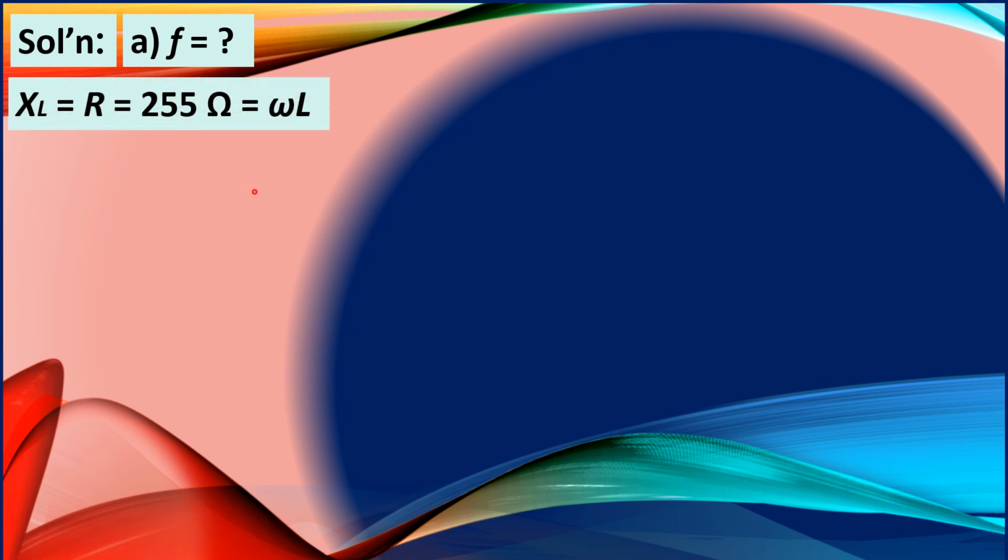All right, so our solution for question letter A, we're looking for the frequency, small letter f. We first determine the inductive reactance X of L, which according to the question is just equal to the given resistance R, equal to 255 ohms.